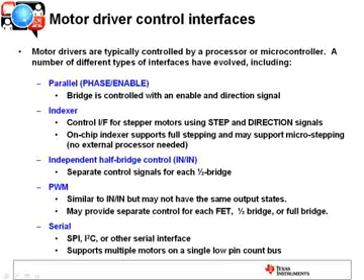You've also got N1, N2 type interfaces. These provide independent half-bridge control. They're somewhat of a legacy interface. You'll see PWM interfaces referenced. Now those can be very similar to the N1, N2, or they can be different. It just depends upon the H-bridge logic output states.